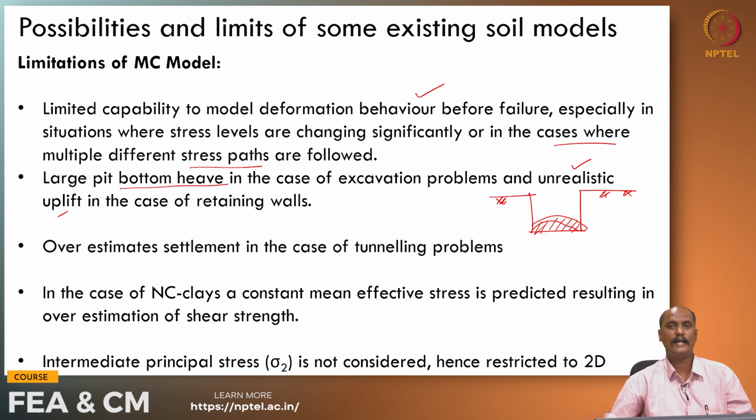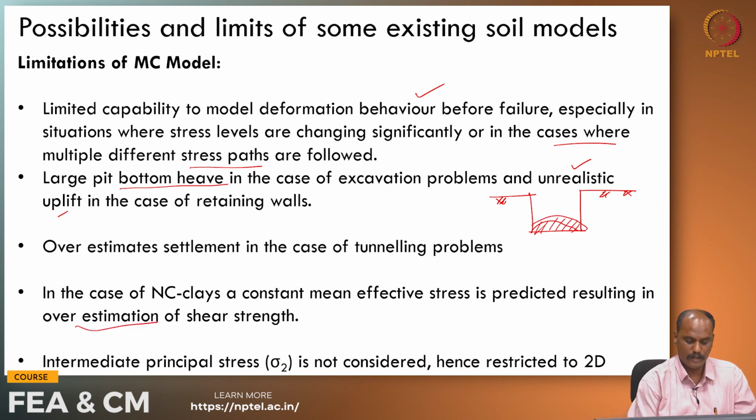This is actually not the case for normally consolidated clays, especially in undrained behavior. As a result, the shear strength is overestimated. This is quite dangerous when modeling normally consolidated clays, especially under undrained conditions.